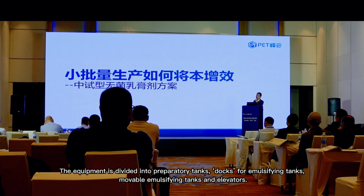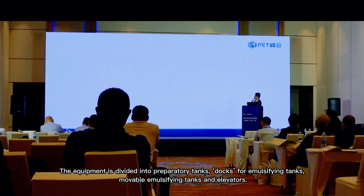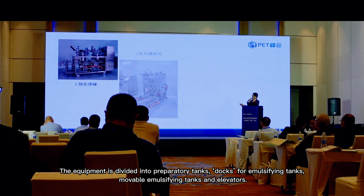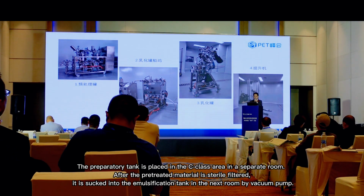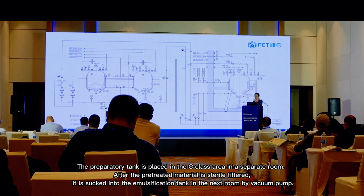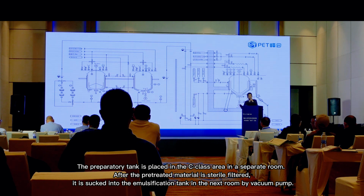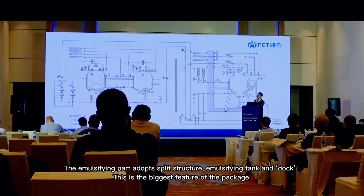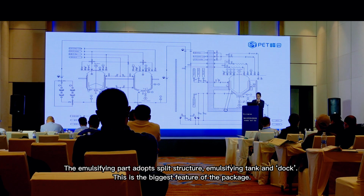We made full use of the characteristics of simple structure and small volume of the fifth-generation emulsifying tanks and designed such a structure. The preparatory tank is placed in the C-class area in a separate room. After the pretreated material is sterile filtered, it is sucked into the emulsification tank in the next room by vacuum pump. The emulsifying part adopts a split structure, emulsifying tank and dock. This is the biggest feature of the package.